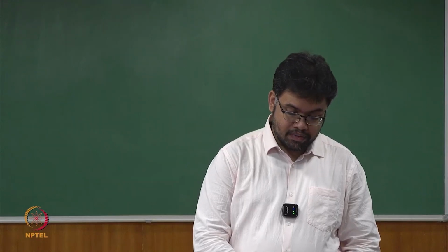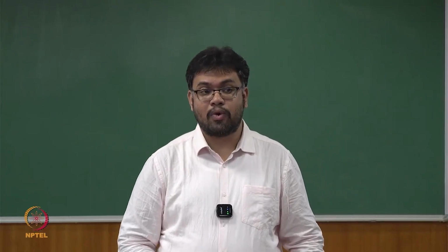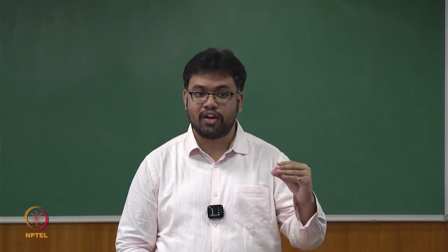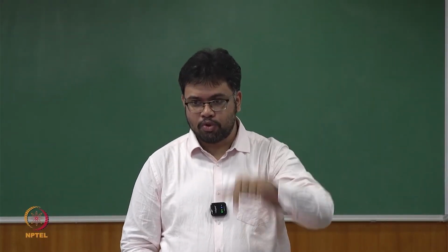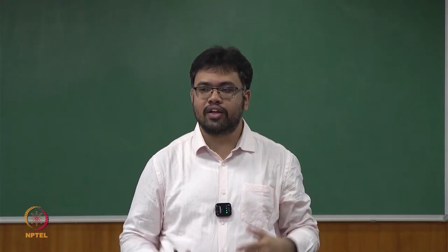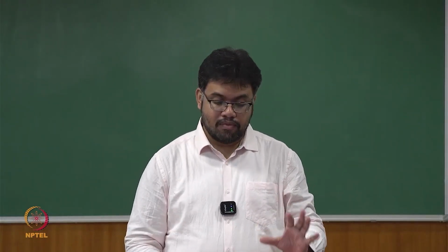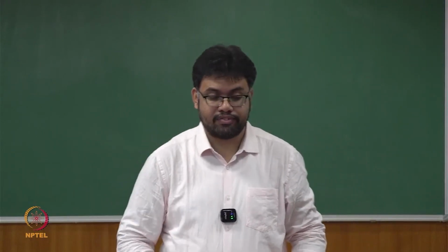So the modal participation factor represents the amount of force acting on that particular mode, correspondingly to that mode, whatever the single degree of freedom system is there, how much force is going to apply on that. So that is the meaning of the modal participation factor.